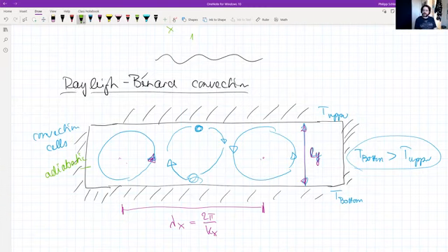So this is the second case. What we need for that is, of course, to add another equation to the Navier-Stokes equation. So we're not only considering the velocity, but we also need to consider the temperature as an additional quantity that is being transported. And how to do that is explained in the manual. Essentially, you consider the temperature to be a scalar.